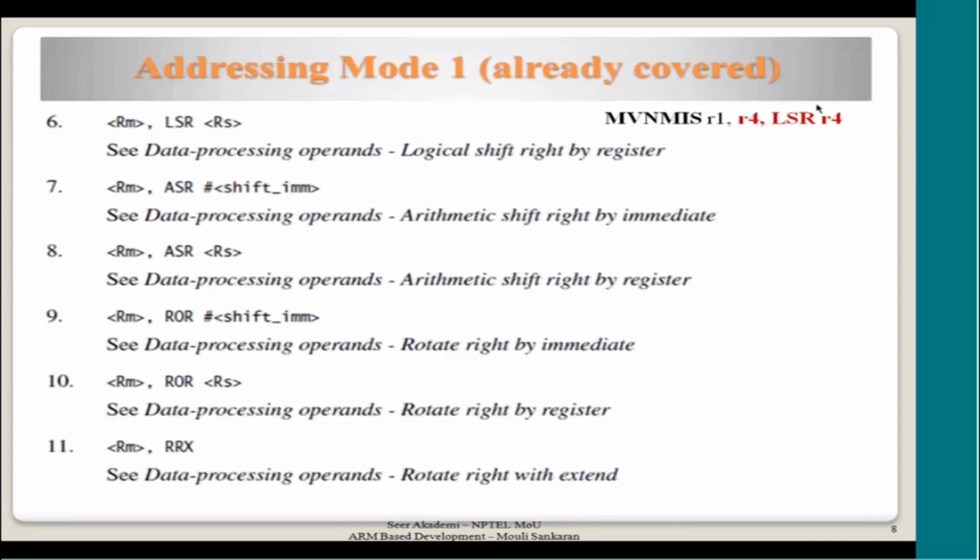That means the inverse of every bit is taken, and then the value is written into R1. Now what is this condition? MI is the condition code for minus. That means if the sign flag is set, that is, there was a negative result from a previous operation somewhere, only then will this be executed, and based on this move, any flags will be affected based on what is written into R1.